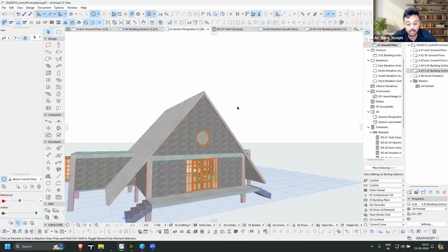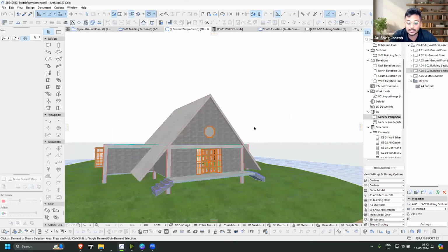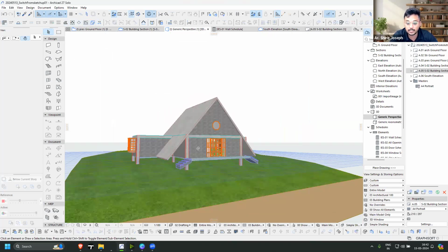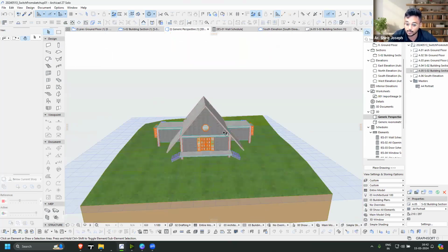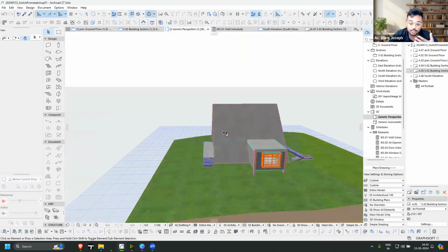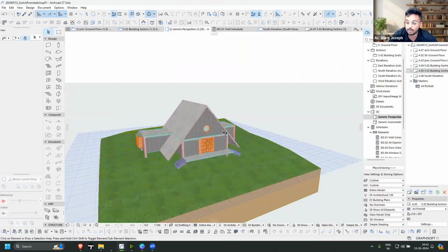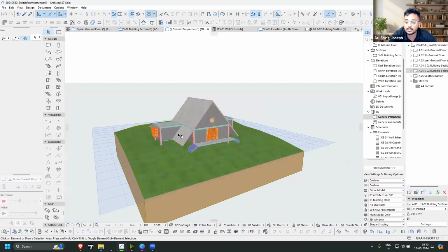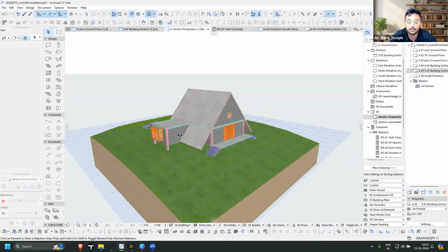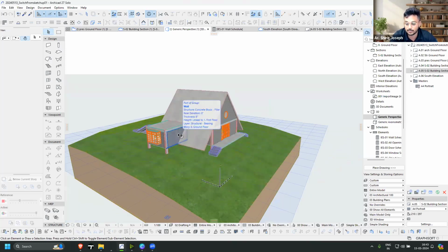And then if I get back to 3D, you will be able to see the same Excel data has created this model directly. This is one of the major advantages when it comes to the modeling part. Instead of taking the contour drawing and converting that completely into a site model, in just 2-3 clicks you will be able to get this data if the surveyors can give you the XYZ. That is the first thing they will have right after they do the survey.